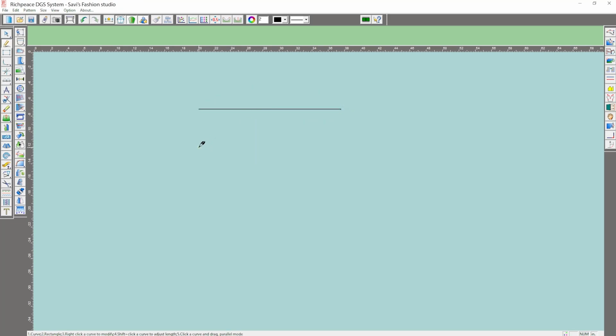Okay. Now you can also draw a curve with minimum 3 points. So click, that is left click on the mouse, click again and right click to complete the curve. Again I start. Now if you right click the mouse, the symbol changes to a T. Now this means the line will only go straight horizontally or vertically, or you can draw at a 45-degree angle. You cannot draw in between and you cannot draw a curve. So to complete the line, left click, okay.